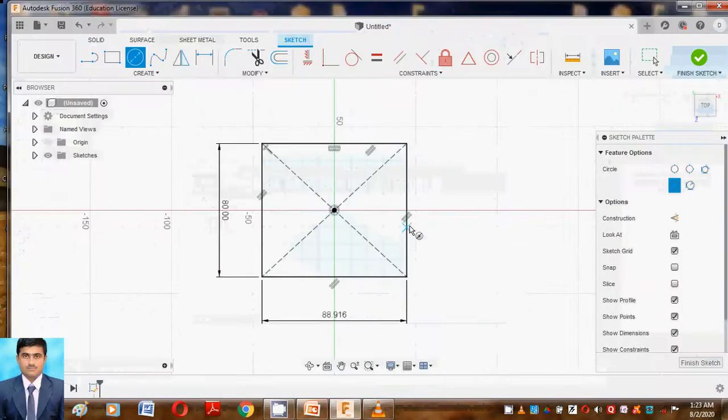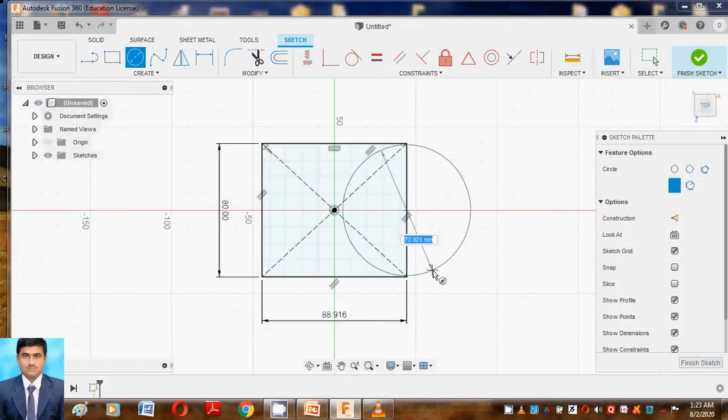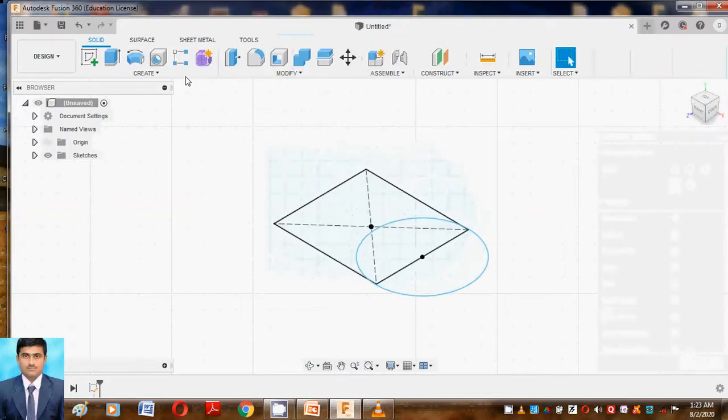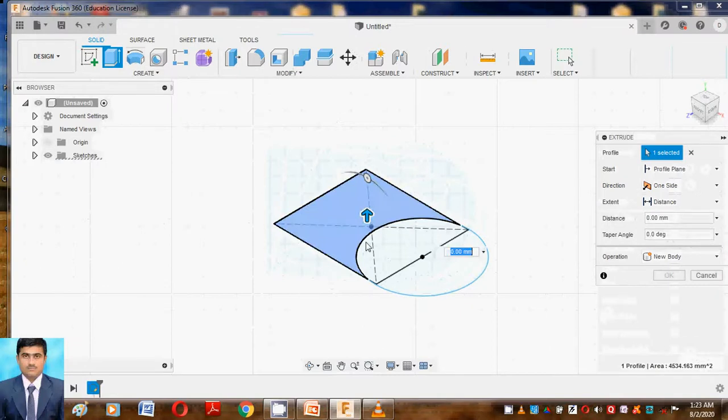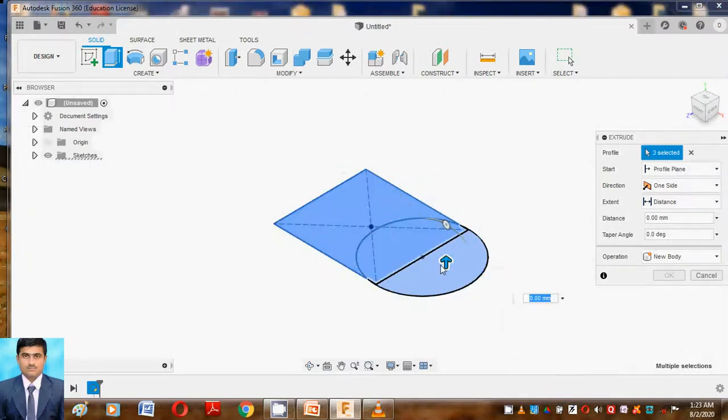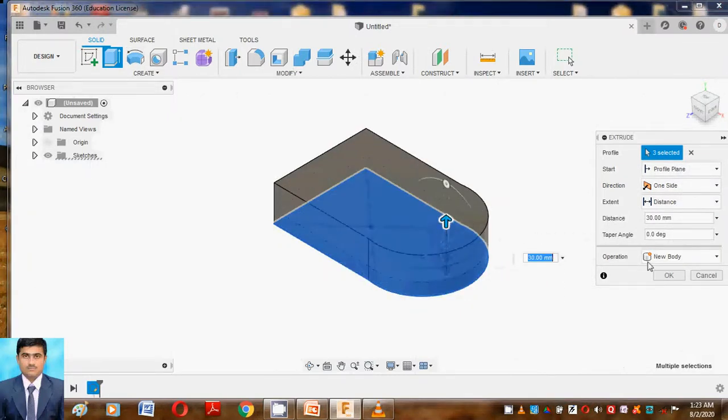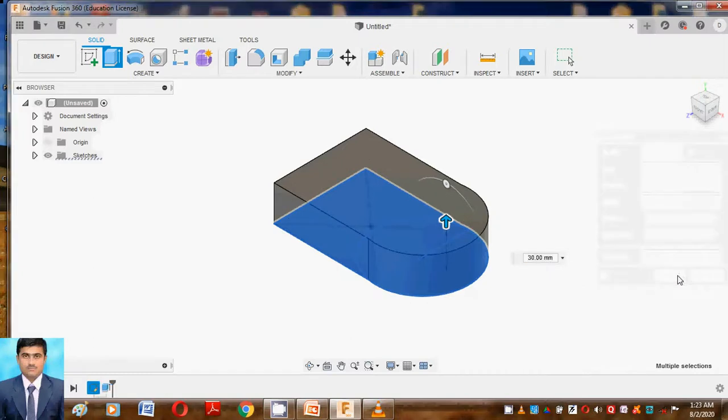Okay. So enter. Again we use this circle because we require this shape. So for that purpose we use this shape like this. Here, after pinching, you have to create this circle part. After that, finish. Then in modeling, create this shape and extrude. So extrude is there. Say OK. So this is the final shape.